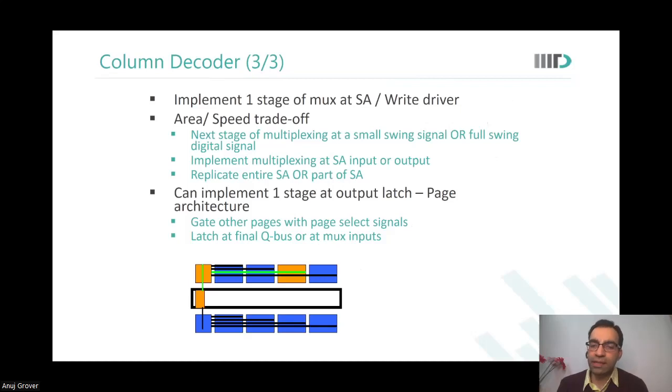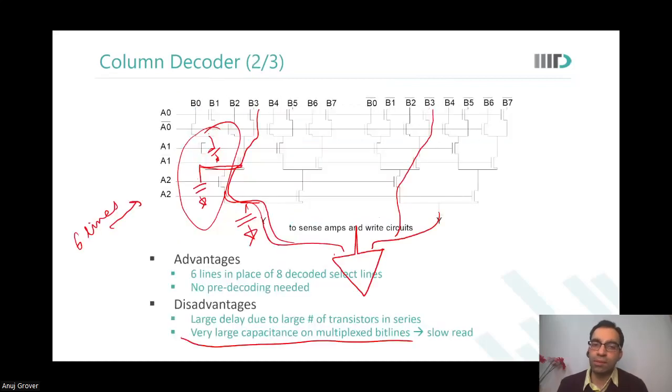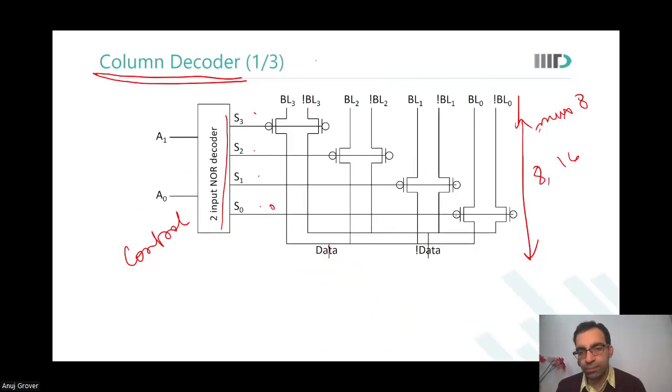So what is typically done is, sir, in the previous slide, you said earlier that that PMOS is not going to put a strong 0, right? So why are we not using NMOS here with PMOS also? Yeah, you have to use it. I just said in this implementation it is not there, so you have to use the NMOS also. So you have to use transmission gates. Sir, I do not understand why we are not using this kind of column decoder. Who said we are not using? Did I say we do not use?